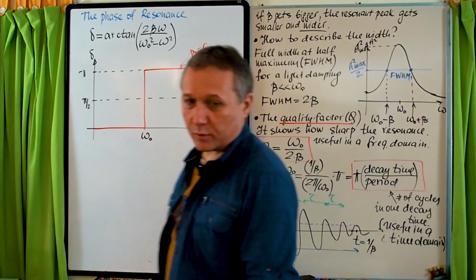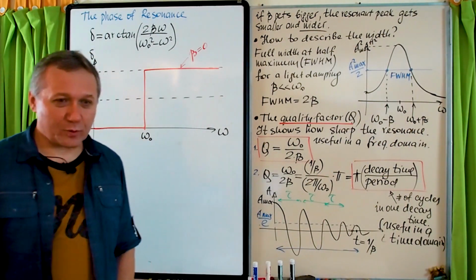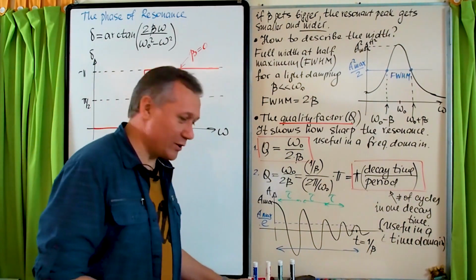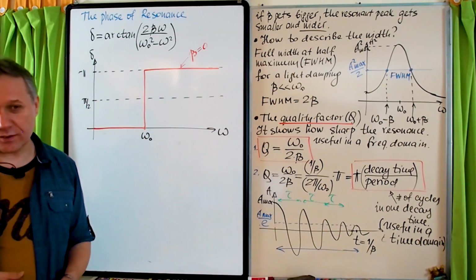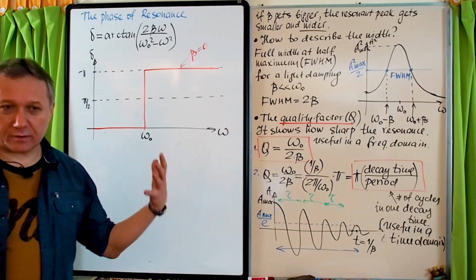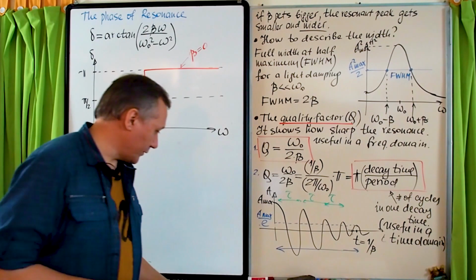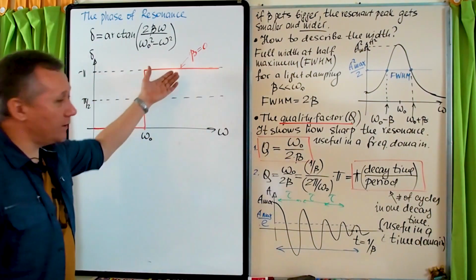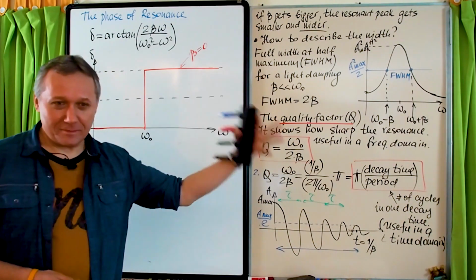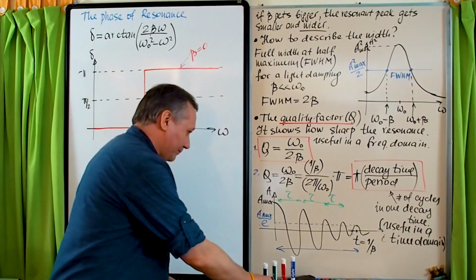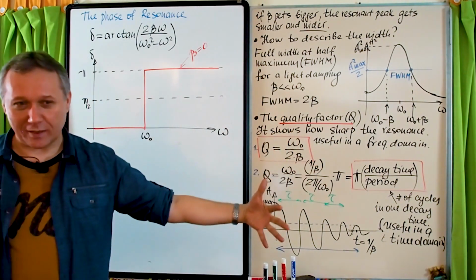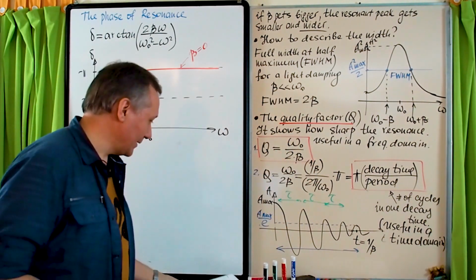It still has inertia, so it's not capable of responding to the fast changes in the frequency of the driving force. So over here, the system will be out of phase completely: the driving force is at the maximum, and the system is still at the other side.